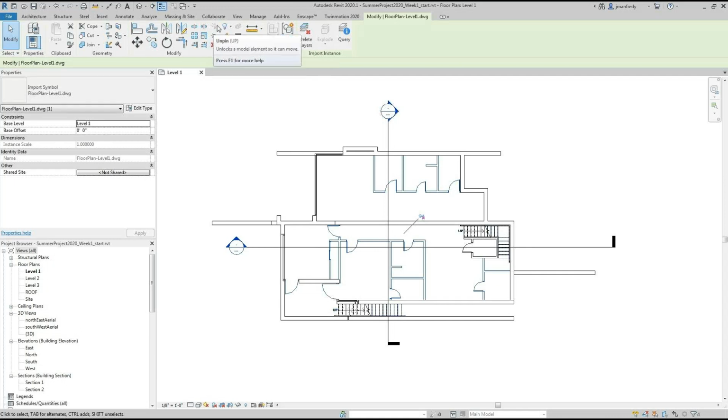I'm sorry, there's a pin and unpin up here at the top, or UP. One command, if you type the command in AutoCAD like UP, it automatically launches the command. In AutoCAD, you have to type something, you'll see the word being typed, then you have to enter, and then it'll do the command. In Revit, there is no return. You simply type the shortcut, and it'll do it instantly. And I gave you a PDF of shortcuts. And you'll learn what those do as we go through the class.